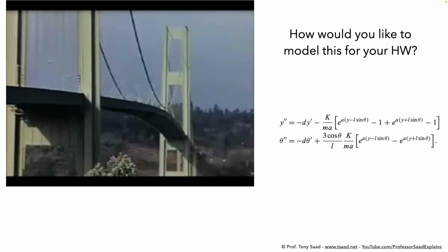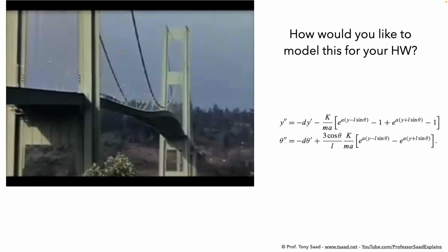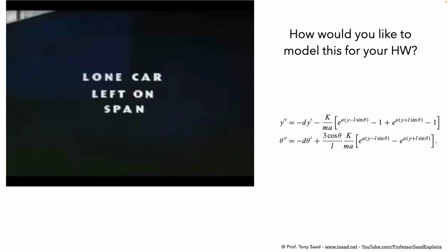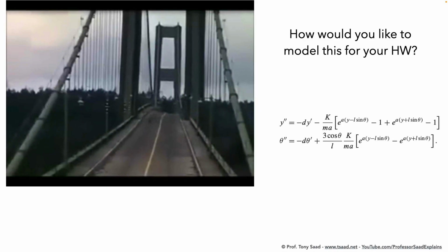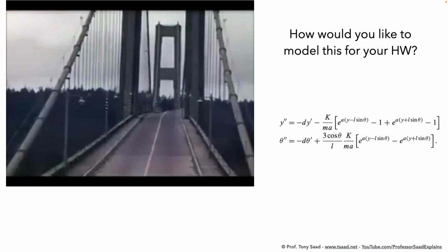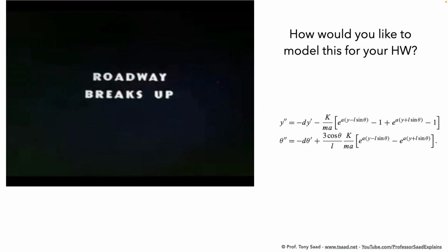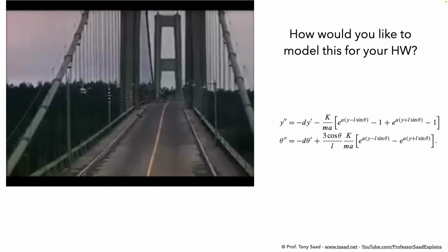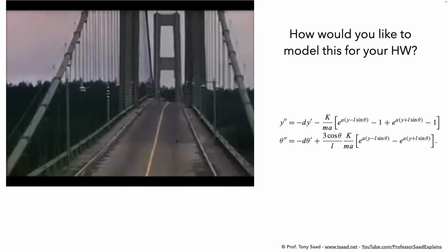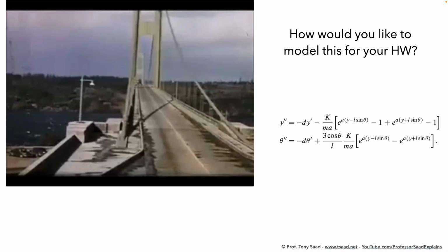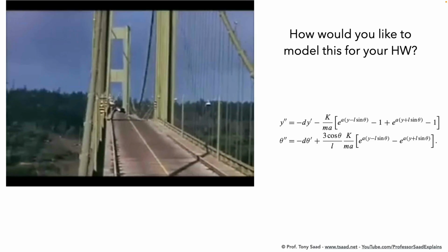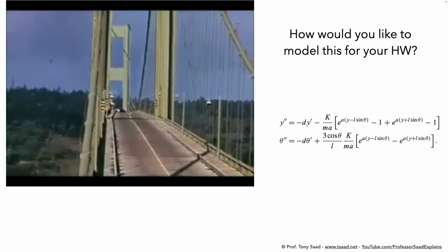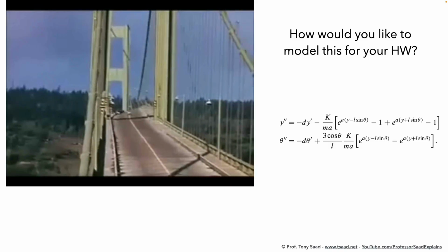So as flow is crossing the bridge from the other side to this side, it's fairly uniform, and then it hits an obstacle. What happens, it creates an oscillatory flow behind the object. So this happens on things that have square cross-section, cylinders, airfoils, anything. So you get a bunch of alternating vortices on the other side, and those change direction due to pressure gradient oscillating. And so this is an example of this causing a disaster.